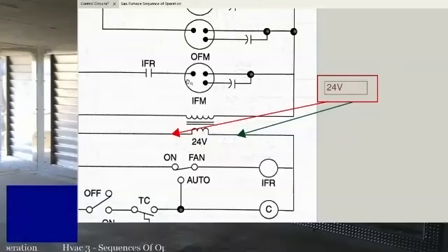If you're dealing with a three-phase unit, check that you have low voltage at your transformer first, because that'll still tell you if your primary main circuit feeders are in there, and then check all three phases to make sure those are good too. That makes sense?